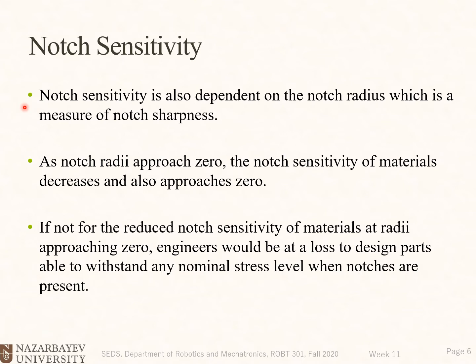As the notch radius approaches zero, the notch sensitivity of materials decreases and also approaches zero. If not for the radius notch sensitivity of the material at radii approaching zero, engineers would be at a loss to design parts able to withstand any nominal stress level when notches are present. Okay, so it will be more clear when it comes to the mathematical formula.